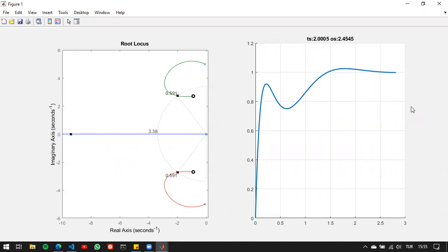Now, you can see that the poles here and the zeros are somewhat close to each other. So, for example, if we pick a higher gain here, for example something like this, like infinite, then what this would do is get rid of the zeros here. And basically, I'm proposing to cancel out these poles here with the zeros of the controller, because the PID controller adds 2 zeros to this system. What if we place them on top of these poles here? Get rid of the poles here.